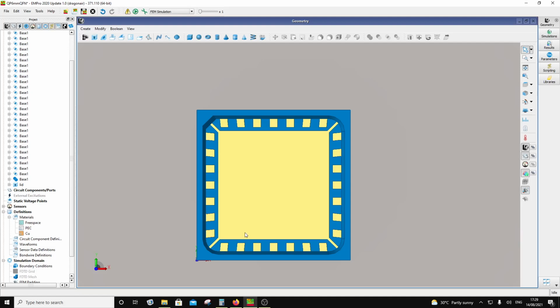So my journey with the design starts with the package, because I want to know where my ground is going to be. I want to know what inductance would be seen in the input and output lines. Without that, I don't design, right? So it is good practice to do the package first and then design it out. Now there is a glitch, a problem here. The problem is, what would be the ultimate size of your chip? The size of your chip, you should have a rough idea.